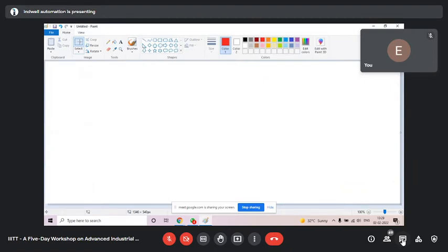What is the range of flag M0? I told you, no. In Mitsubishi, I have seen 500, 600 also, there is no issue, but the type of flag will change. After 500, it will become a retentive flag, but below that, it would be a normal flag. So the range is large. We have a large range of flags we can use. No problem.